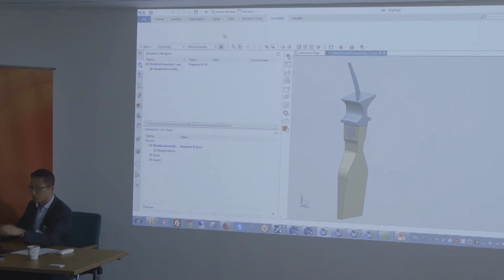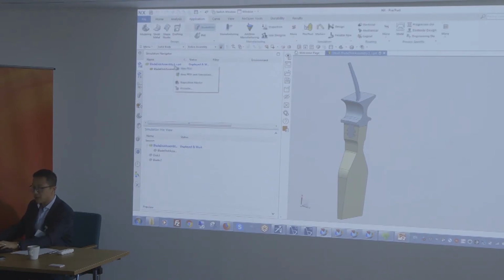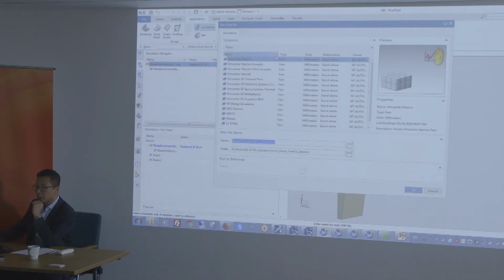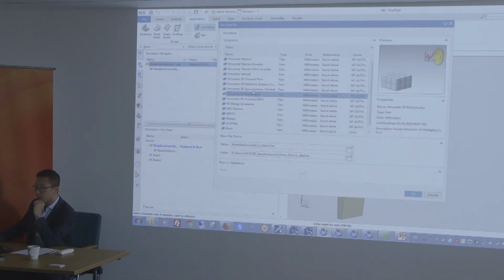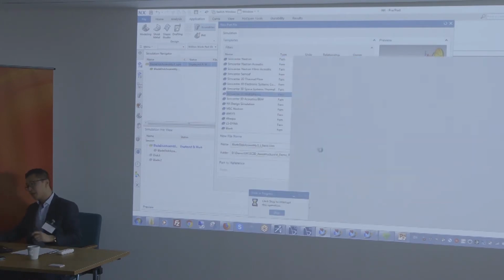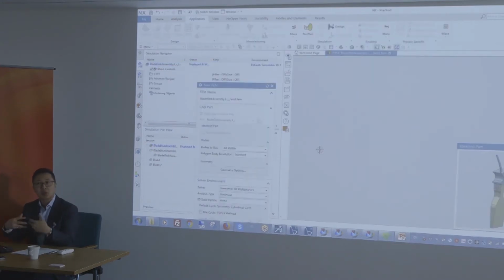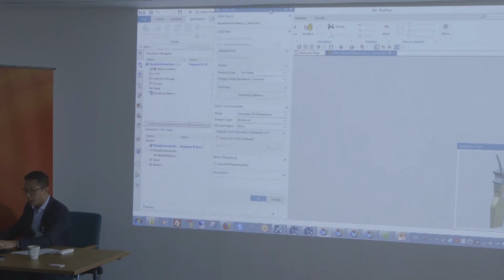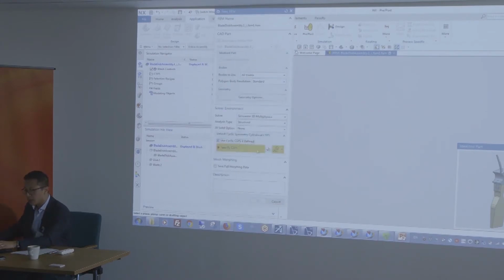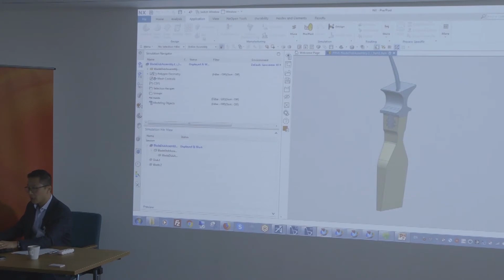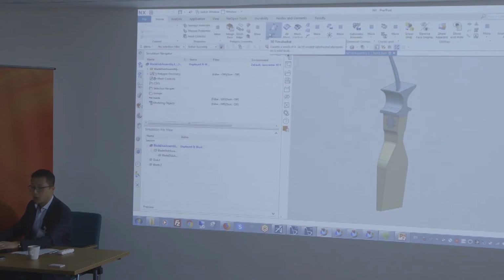So what we'll do is we'll go directly in our meshing environment by creating a new FEM. In this case, we'll want to use a multi-physics environment, and the only difference is that it exposes different elements, right? Elements compatible for both analyses. In this case, it's cyclic symmetry, so we can do this or not, right? So it's up to us to determine what kind of analysis we want. And here, we can mesh.